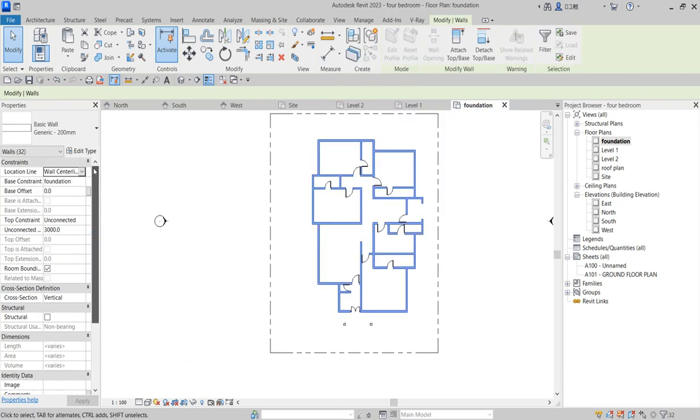So here is what to do. Align this one to up. Then you say unconnected. You change the unconnected. You may remember the whole height is 1000, and we have slab of 200 thickness. So 200 mm thickness. So what you do to the left is 800. So you just type 800 here.